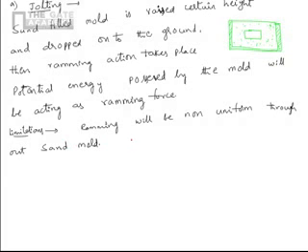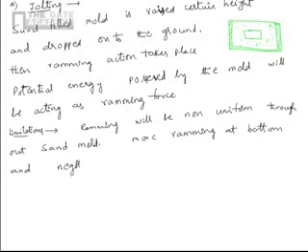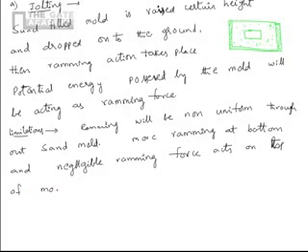There is more ramming at the bottom, and no ramming or less, negligible ramming force acts on the top of the molding box, which results in loose sand on top.